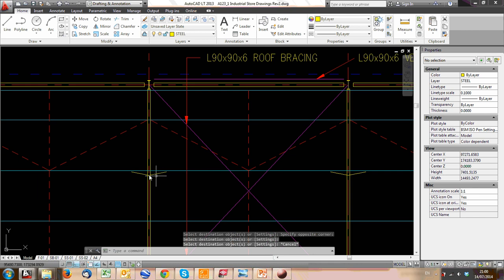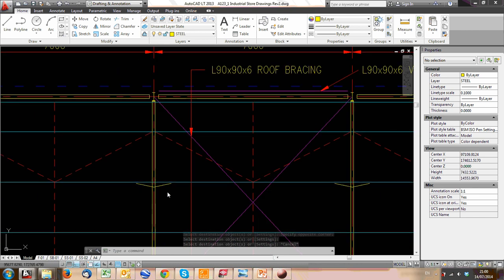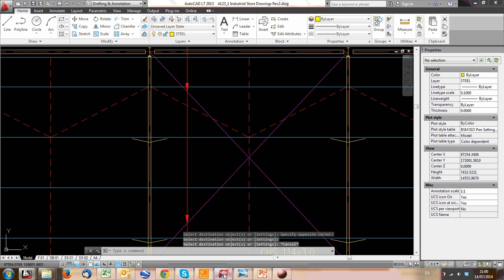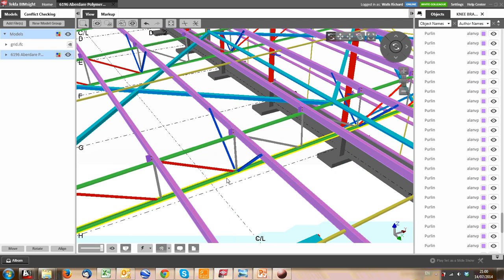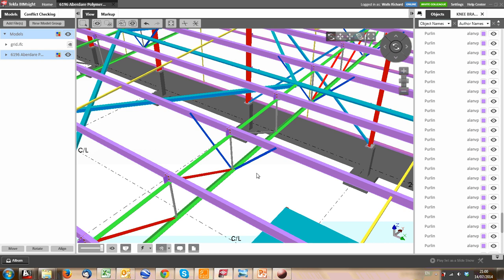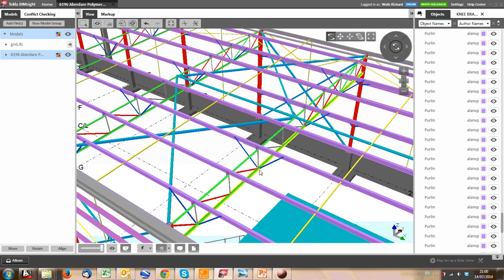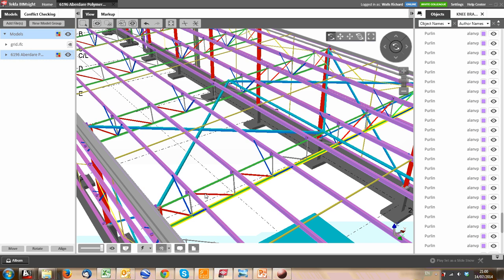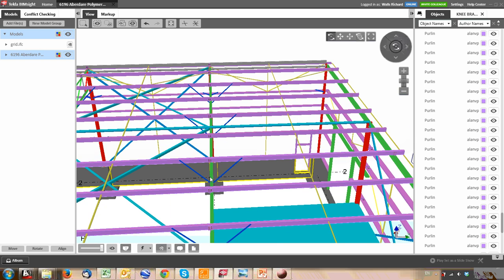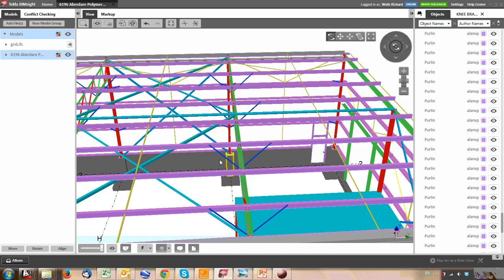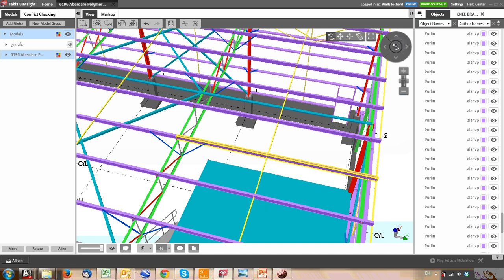Knee braces, as we were discussing in the last lesson, they're these little V's that keep our truss stable. Let's zoom in on one here. There we go. There's one of the knee braces that actually stabilizes the truss. It reduces the effective length. The knee braces can be used to support the purlins, but then you put one on every purlin. You must actually design it as part of the system then. This is just sized by slenderness at the moment.